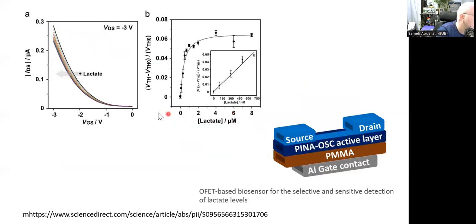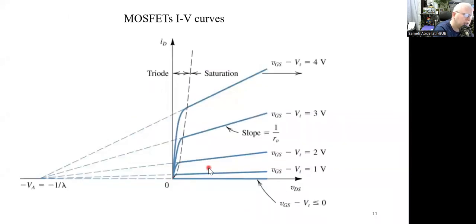We can see here the effect, which is very, very interesting, because you have an IV curve varying without varying the biasing condition. Usually, it is very easy for us as electronic engineers to vary the IV curve. For example, let's go here to this curve, or this one. Here we have a family of curves. But here you have a family of curves simply because you have variation in the biasing condition, typically the gate voltage. You change the gate voltage, that's why the IV curves change.